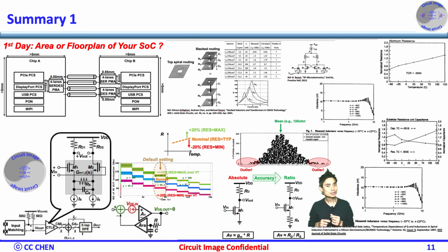Here is a summarized image showing you why the process evaluation for the RLC passive elements is a must, especially in your first day of the design phase or even the first day of your project planning phase in choosing which process you would like to go with in your new project. If you are doing a new design from scratch, the estimated area of the RLC can help you decide if your circuit topology is reasonable to implement in an amplifier, biasing, passive filter, and LC tank, etc.